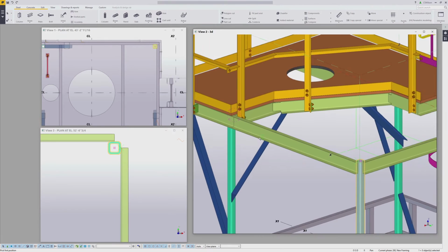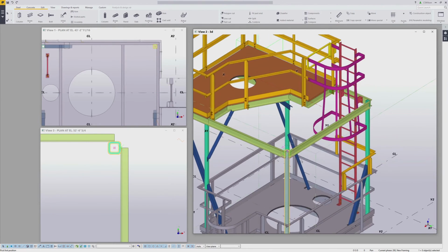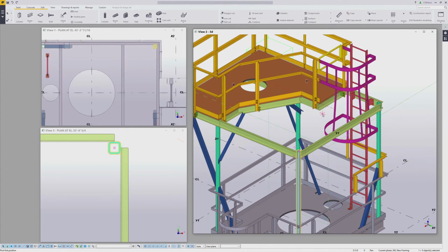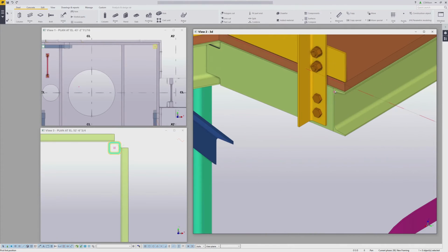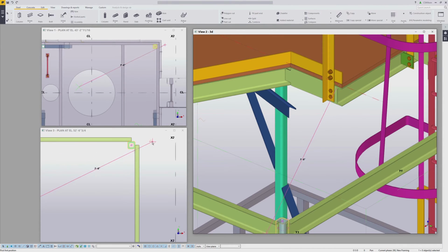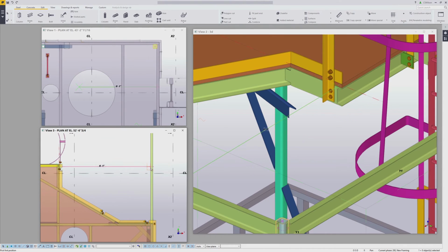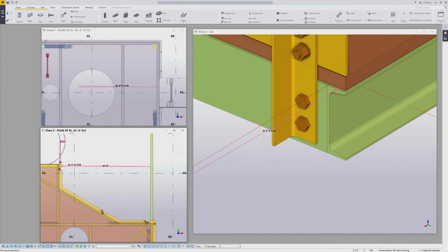Okay. And then I want to also hold down the control key at the top of this member to give a control point. Come back to my plan, make sure that I'm perpendicular, give a point, and then an end point.